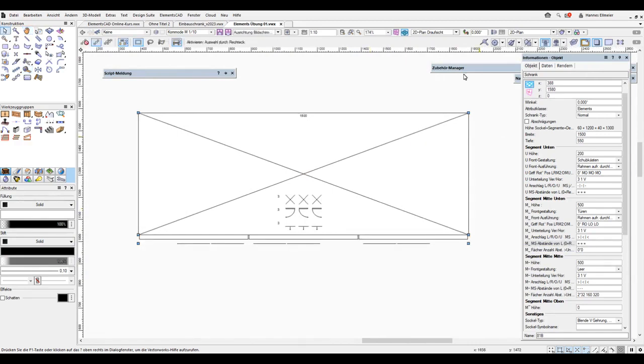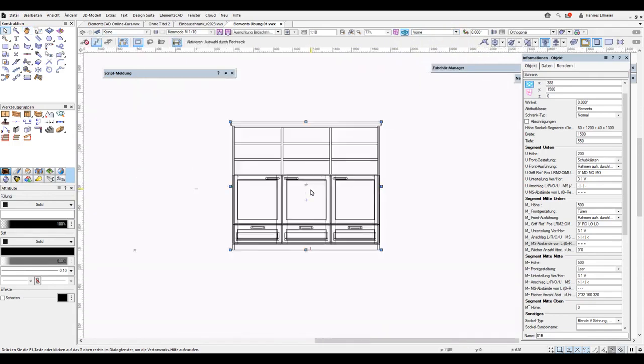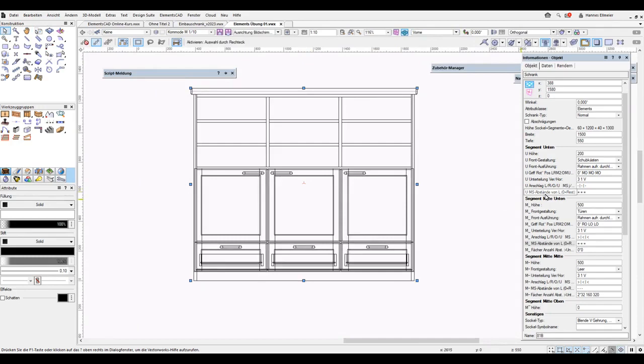In the front view, we can also change it. To do that, we go into the segment and select a 90-degree angle here, and in addition, we have the handle position in the top right. Instead of O, we could use M for right middle, left middle. If I were to change the stop direction now, the recommendation is to use an L instead of an arrow, a capital or lowercase l, and then it will be converted into the needed checkmark.